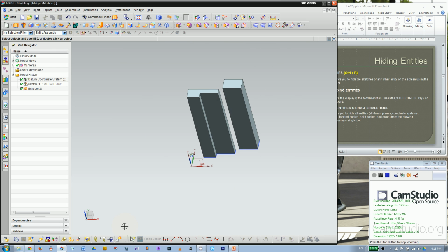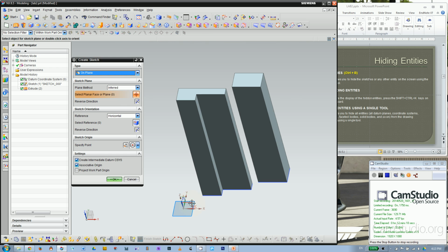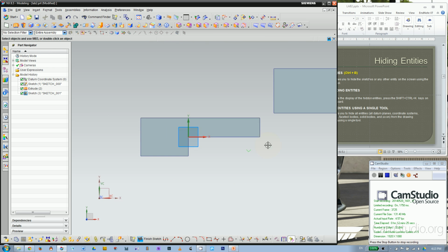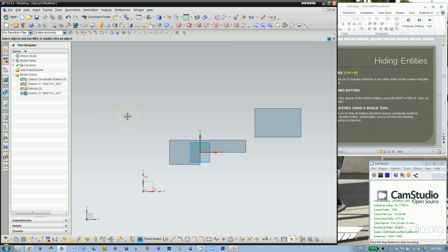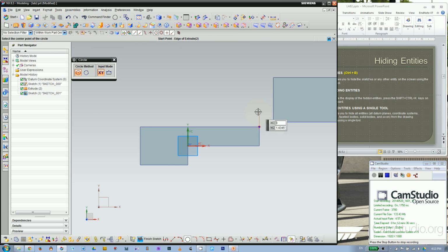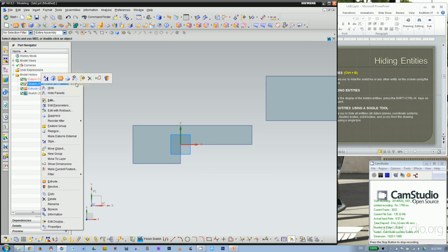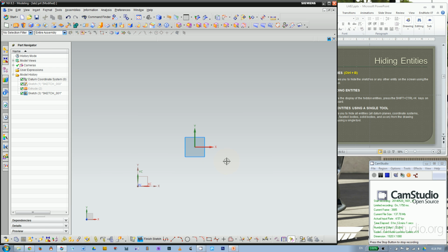And let's say I have another sketch on this top surface. Just a quick reminder, a sketch can be built on a datum or a surface face, right? So I'm gonna build another sketch here, and you can see the solid, and you can see the first sketch in your second sketch, and if you draw anything, it will snap to that. Sometimes you don't want the interference from the background, so what we do is right click anything you want to hide, and that's the icon for hide. Also you can see from here, so hide the extrude, also hide the first sketch. Now you have a very clear working space.